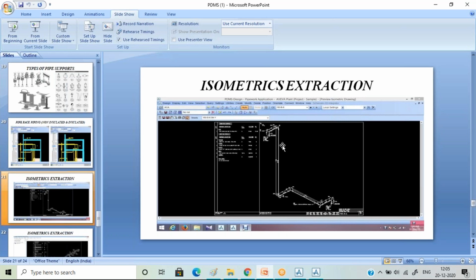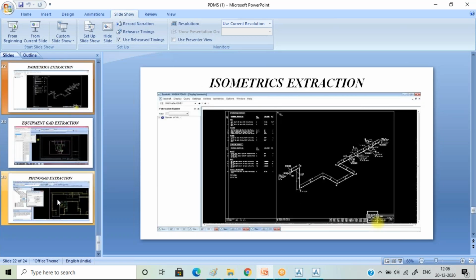how you can check your isometric without even coming onto the draft section. Okay, because simply what is the problem, that when we are taking out isometrics, we are taking them out in different modules. Different MDBs we are choosing for this. So for taking out isometric, we choose the Iso Draft module, and for taking out JDs, we choose the Draft module. So this is what we do.